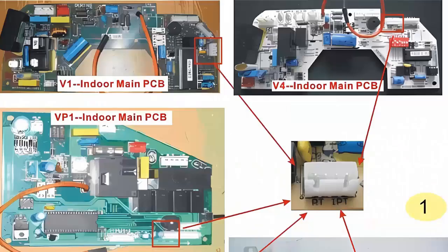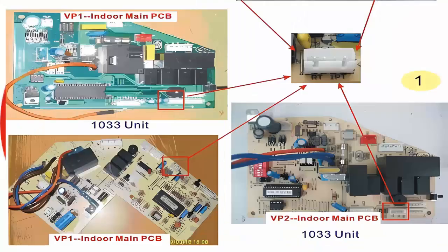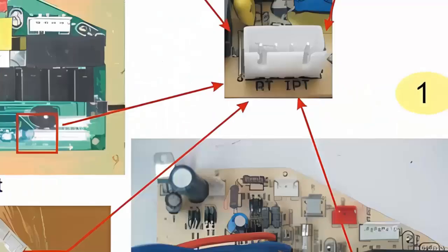3. Check the position and connection of the sensor located on the electronic board of the indoor unit. Make sure that the room temperature sensor connector is inserted correctly into its slot. If it is loose, reinsert it firmly. Recognize the connector because the indoor unit temperature sensor connector is also very close. Turn on the equipment and check if the error reappears.